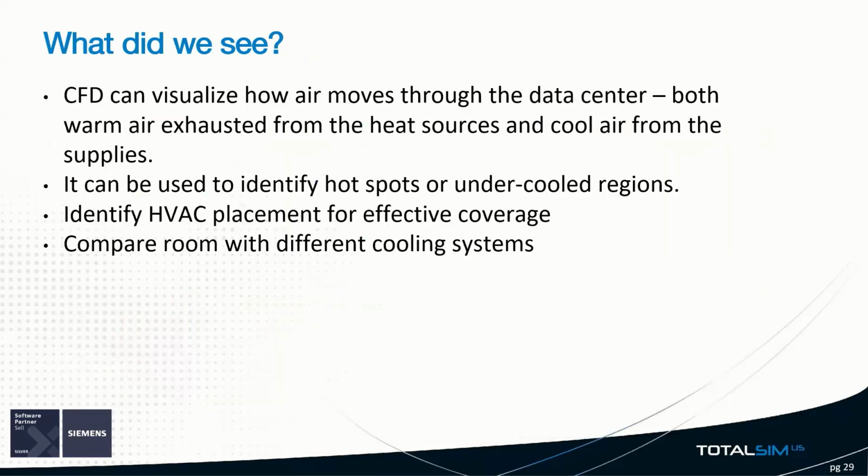So what do we see? With CFD, we can see how the cold airflow from the cooling system interacts with the warm airflow exhausted from the equipment. We can identify overcooled and undercooled regions and quickly make modifications to design and then reanalyze. CFD can be used to compare different types of cooling system, as well as their placement and sizing.